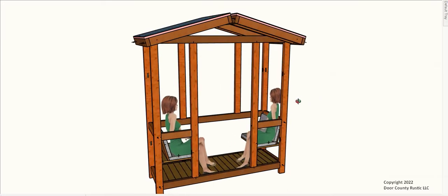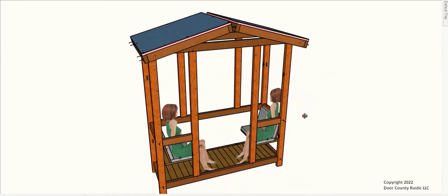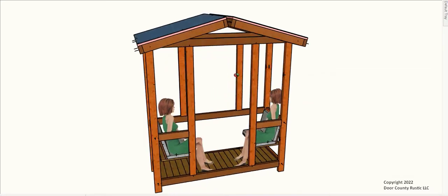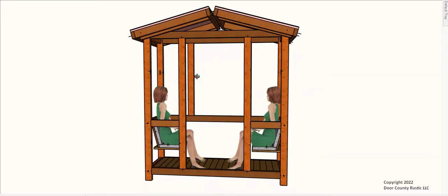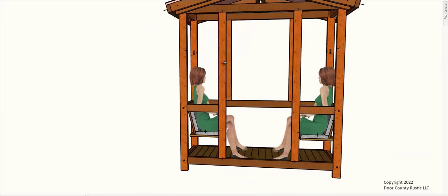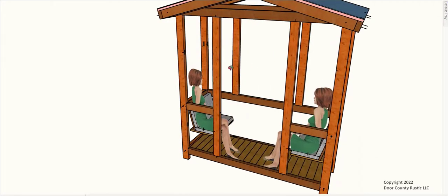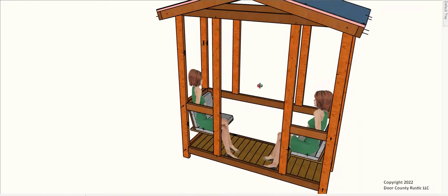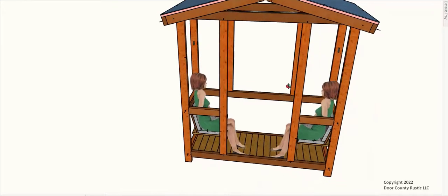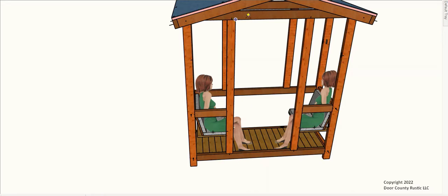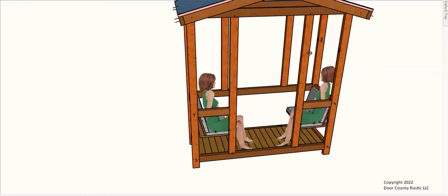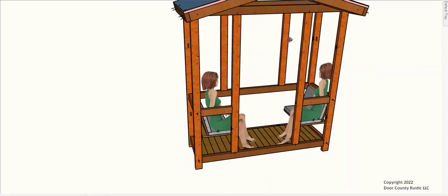This is the standard rough opening for a walk door, like a storm door, like a Larson storm door, or there's also some really cool retractable screens, and they're designed for an 80-inch opening, and then the opening in between can be a variation anywhere from, I think, around 30 inches on up to 36 or 40 wide. So I set it up so that I think they're spaced at 36 inches wide, and so a retractable screen will fit right into this opening.